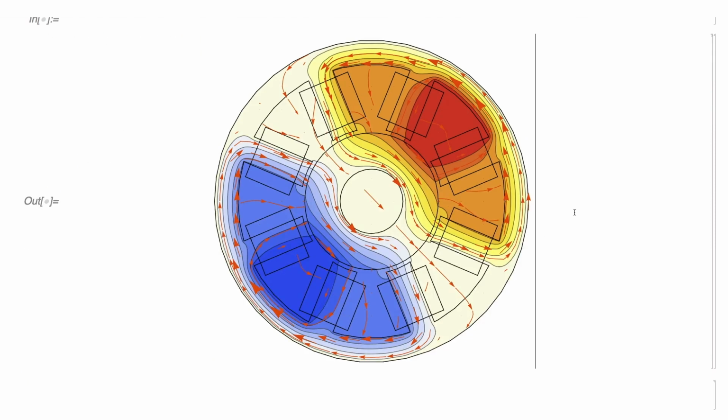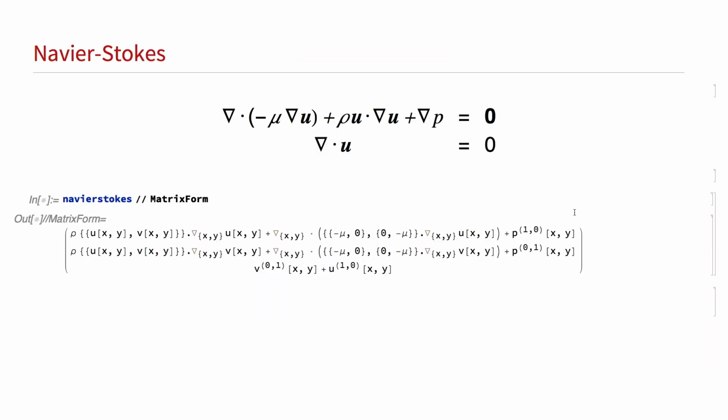All right, so the Navier-Stokes equation. This is the Navier-Stokes equation in the stationary case. The special thing about the Navier-Stokes equation is that the first equation is a vector-valued equation. In the first equation, the pressure P is only available in gradient form, and P is not present in the second part of the equation. So yeah, that makes it hard to solve.